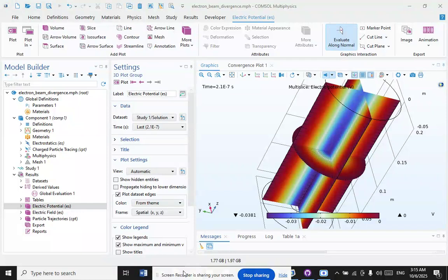However, the high-velocity nature of fluid and vapor flow within the thermocapillary means that this structure can be a source of significant porosity in the finished joint, as vapor bubbles can be entrained within the solidifying material. Mathematical modeling of EB welding presents a unique opportunity to understand the fundamental physics responsible for the compositional, topological, microstructural, and thermomechanical changes that happen during the process.